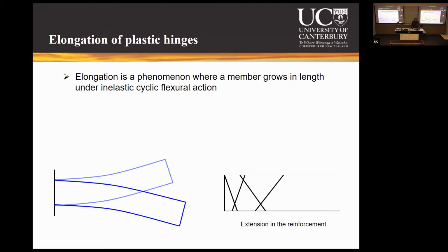For example, when a ductile beam is subjected to cyclic loading and goes from one direction to the other inelastically, the reinforcing bars develop strain, and that strain, when it goes in tension, doesn't unload fully. So the center line of the beam shifts away from where it was in the previous cycle, gradually accumulating that elongation, right?